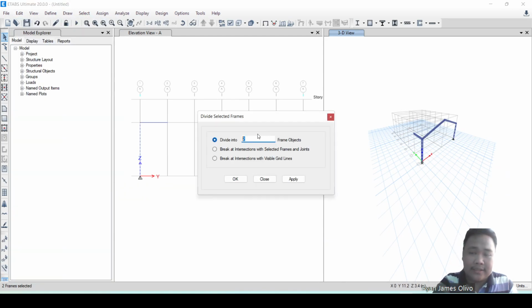We just try to divide it into, I think, 2. So 11.5 divided by 2, that is almost 5 meters. So anyway, let's just run this again if there is a problem in slenderness ratio. But I think 5.75 is enough for something like almost 460 mm wide flange. Anyway, just divide it into 2.